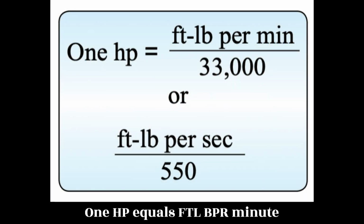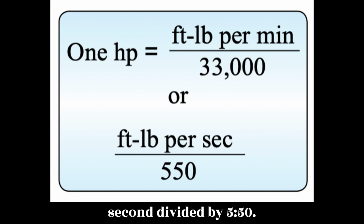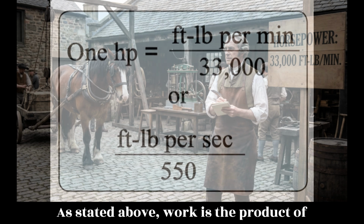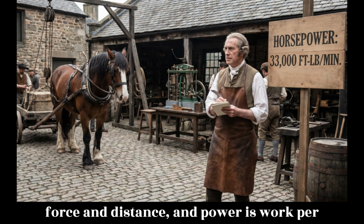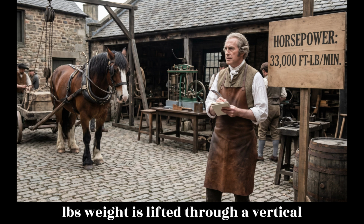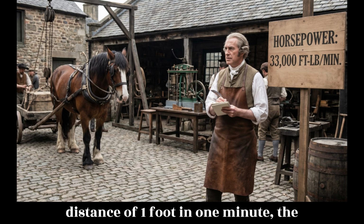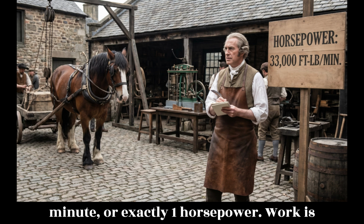1 HP equals FT-LB per minute divided by 33,000, or FT-LB per second divided by 550. As stated above, work is the product of force and distance, and power is work per unit of time. Consequently, if a 33,000-pound weight is lifted through a vertical distance of 1 foot in 1 minute, the power expended is 33,000 FT-LB per minute, or exactly 1 horsepower.